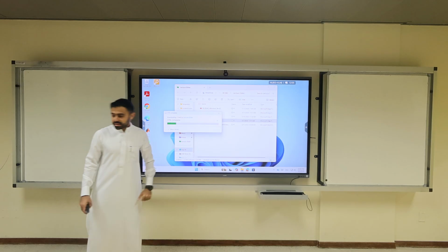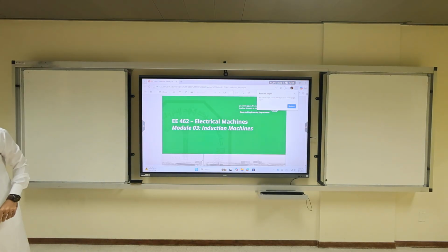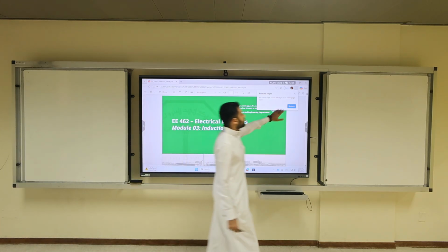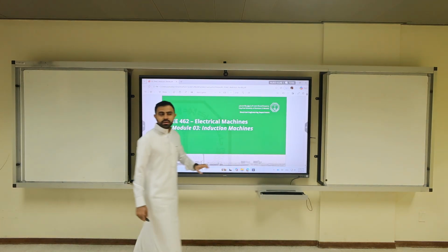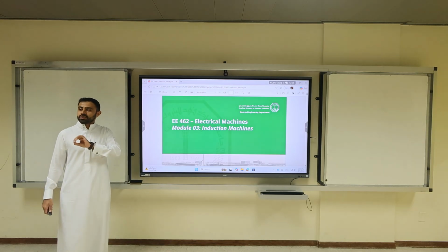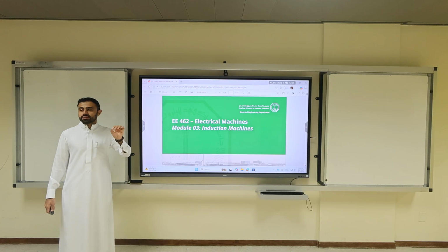So last time we talked about voltage over frequency control. You remember that? And what was the key benefit? The key benefit is we keep the flux constant until what? Until the rated voltage. Anything beyond rated voltage is a violation. You cannot apply higher voltage on your induction motor. Think if you apply 300 volt on your 220 vacuum cleaner, for example. What will happen to it?